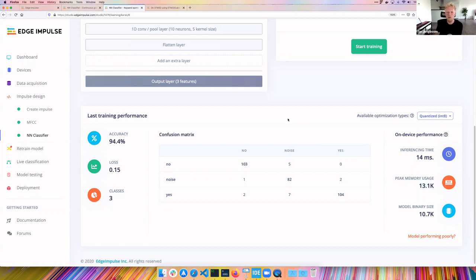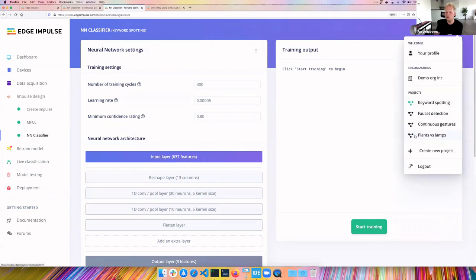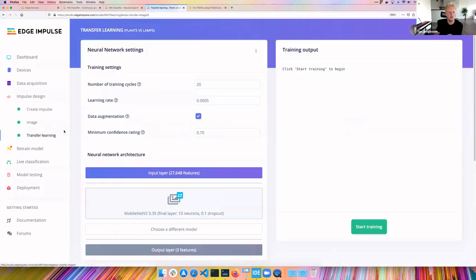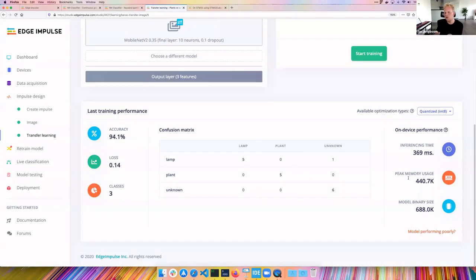And pretty great. And even for complex models like vision models, this is measured on a Cortex-M7 instead of an M4, but we can do this with under half a meg of memory, and this is even on a large model. If we're using a smaller model or a grayscale model, we can get this down to about 120K, which is great because that even gets in reach of Cortex-M4.